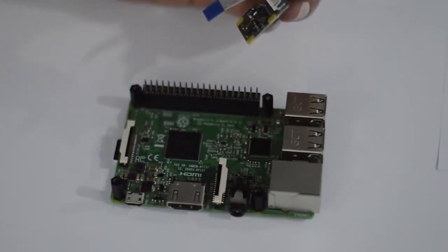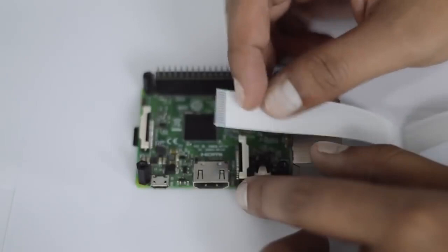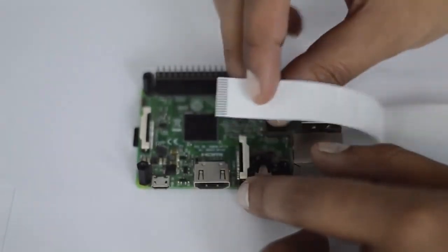There are mainly 2 precautions you really need to consider while working with the Raspberry Pi camera. One thing is to please ensure that the Raspberry Pi is switched off or disconnected before you connect the camera. Otherwise there's a high chance of blowing up your camera. We've already successfully managed to do that once. So please ensure firstly that the Raspberry Pi is switched off and also that the connection is correct. The silver side present here should be facing the HDMI port that is present here.